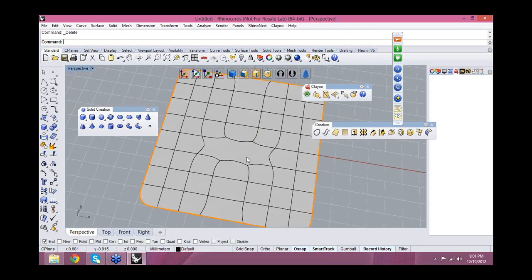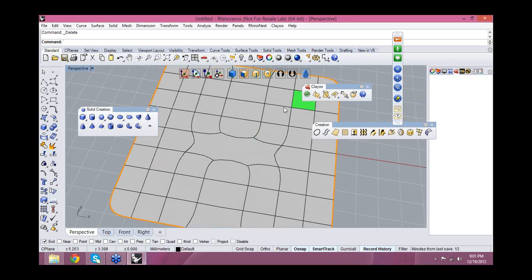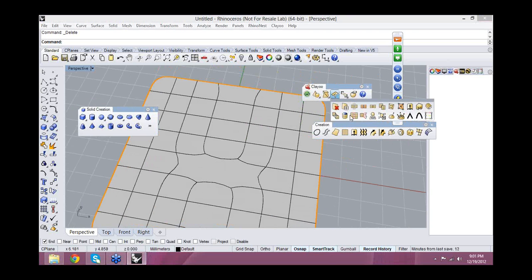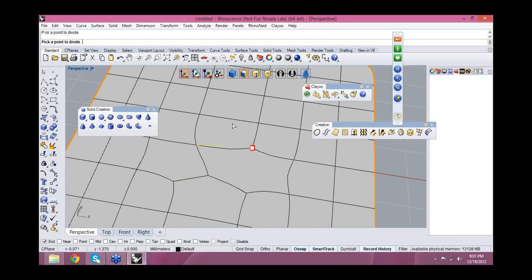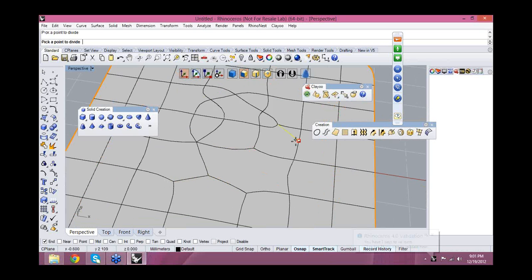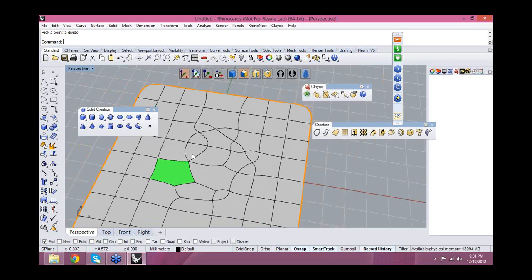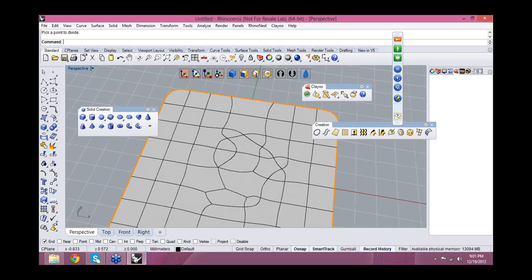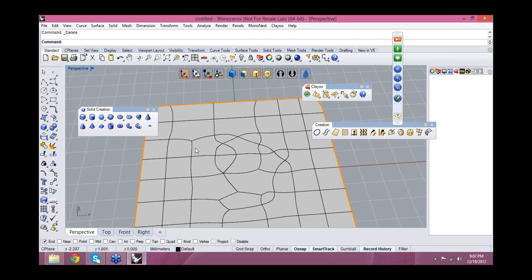And also, you can divide it. You can split it if you want. You have a split here, and this is really nice because you can split as you want. Then, if you convert a NURBS to Clayoo and you have some distribution or some ISO curves that you don't like, don't worry, just select them and delete them. That's it.